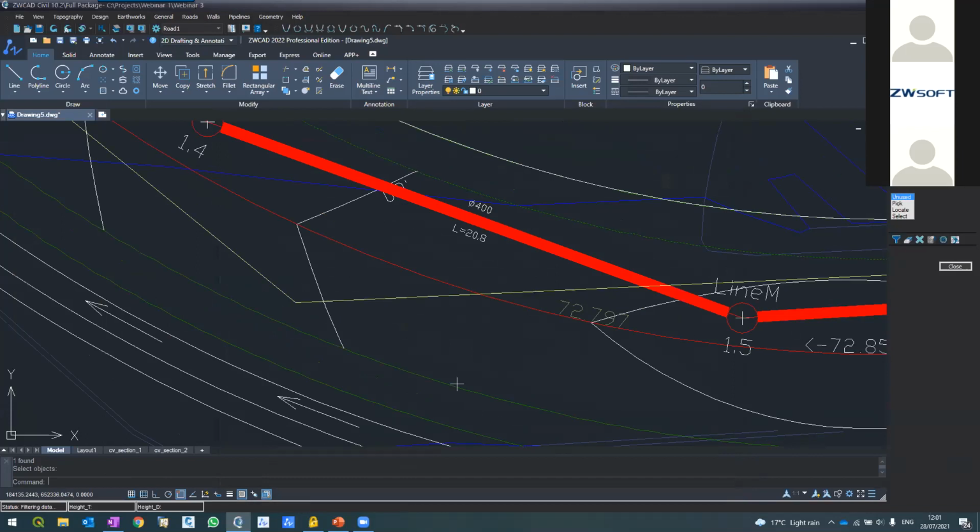So the software automatically identifies 4 points of crossing with electricity, this. Now, I don't know what the depth is, but the electricity company told me that the average depth is 1.2 meter. So I change this to depth, and I'll put here 1.2 meter. And since I'm working in millimeter, I know that it's a 150 millimeter pipe.